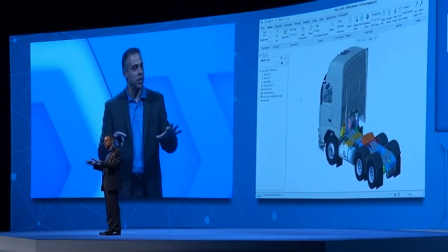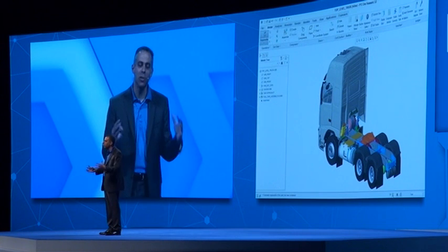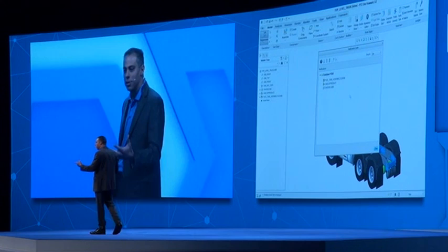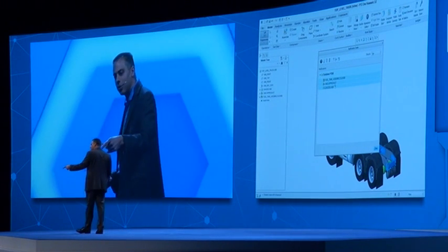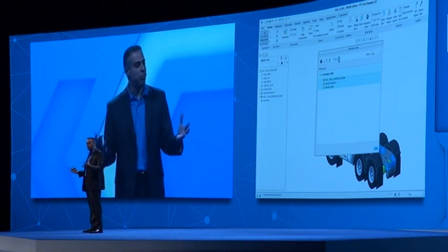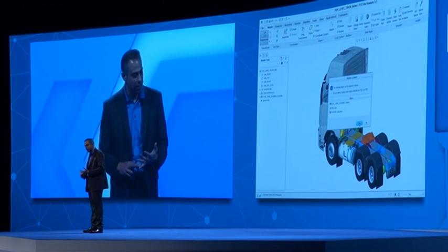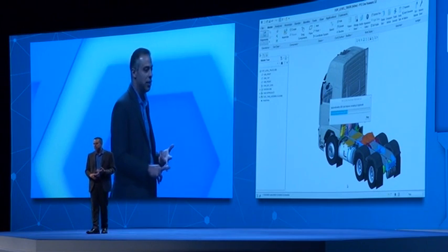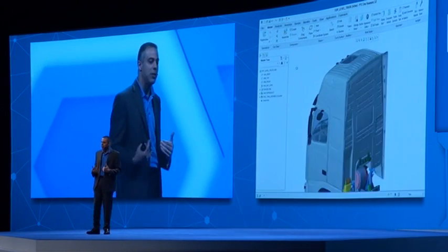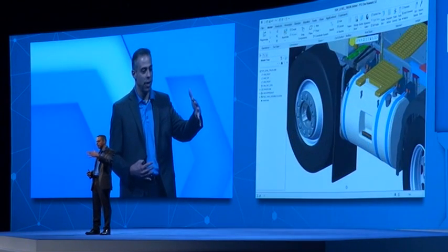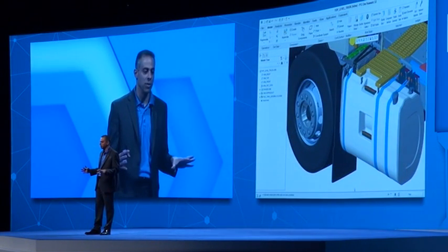Many of you wouldn't do this with your suppliers' and partners' parts because it's so inefficient for changes to come in if you had to design around those changes. But here you see, when a change occurs, when I hit regen, I'm notified proactively of those changes. I have changes in my Creo objects, my SolidWorks objects, and my CATIA objects. And when I regenerate and update those changes in session, you see the CATIA angle of that top cab change right in session, and watch this change on the SolidWorks object.